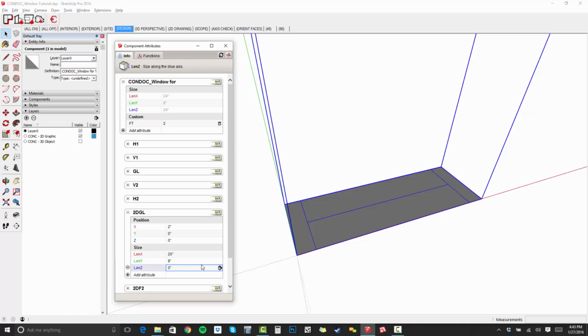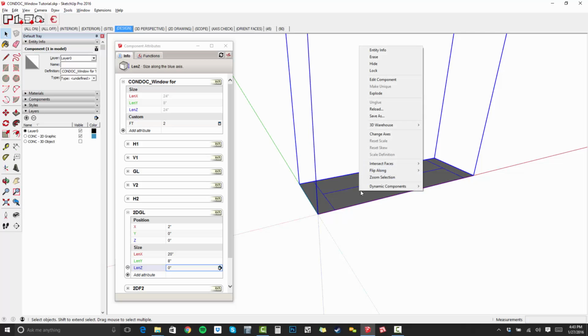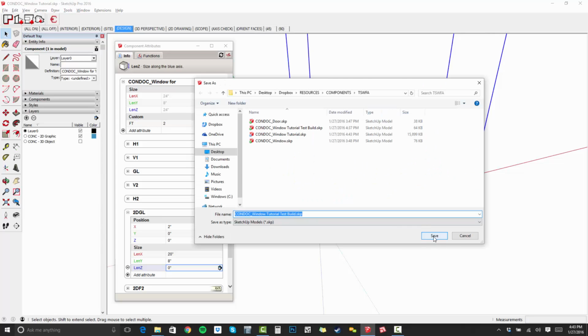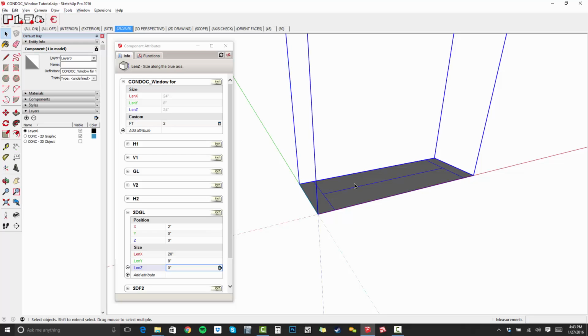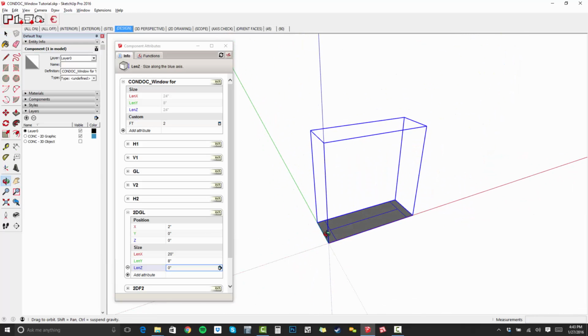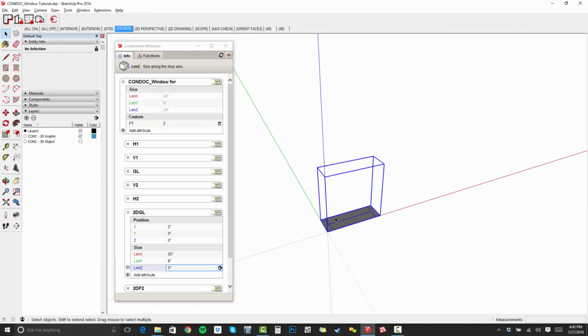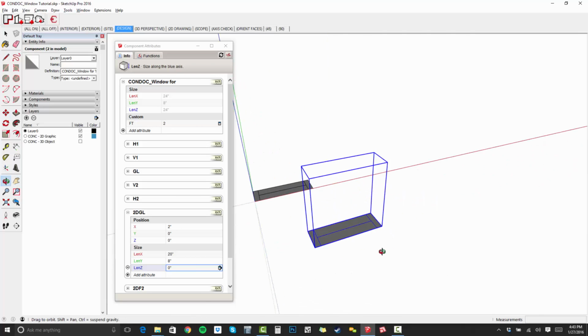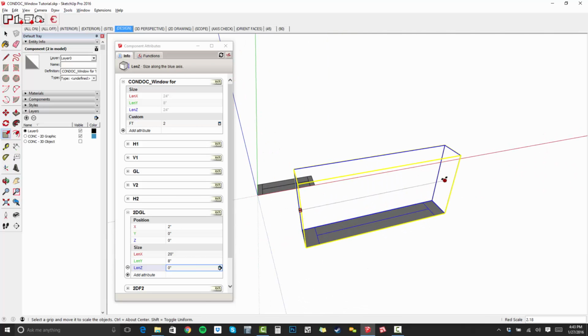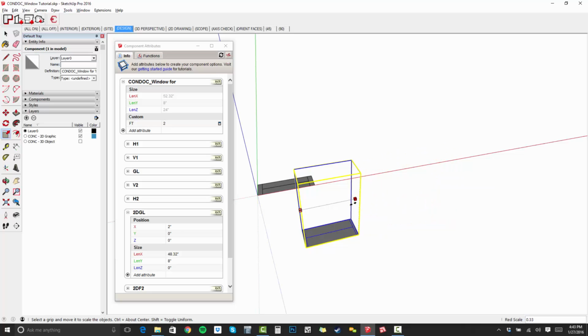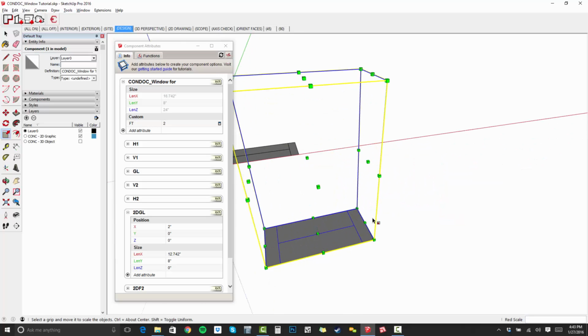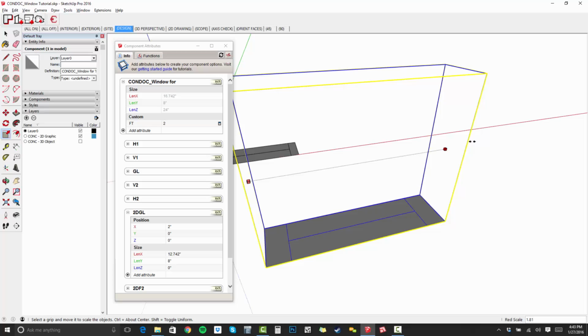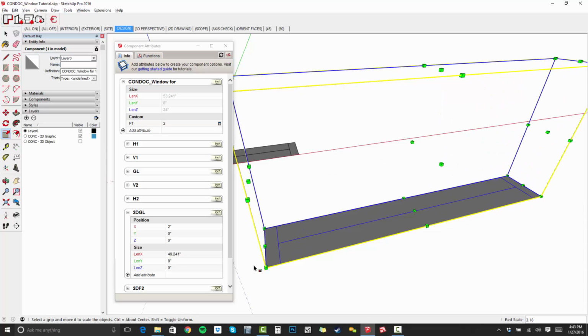0, enter. Okay, let me save that and then do a save as, and we're going to call that our test build. Okay, so I think we're looking like we're in pretty good shape. I always like to make a copy before I start scaling that around. All right, so now check that out. Our frame is rebuilding itself. So when I stretch it way out and it gets big, it recalculates and keeps at a 2-inch frame.